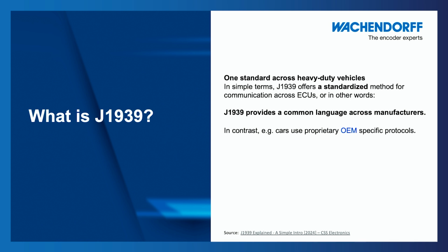It's one standard across heavy duty vehicles. It's a standardized method of communication. So J1939 provides a common language across manufacturers, but you have to be a little bit careful, because there are OEM specific tags and things within that protocol.